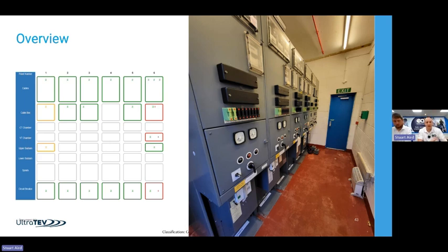So there are two totally independent tests, so we should always be doing a transient earth voltage test and an ultrasonic test to make sure that we can cover both types of partial discharge, both internal and just surface and corona type discharges. So this layout here is out of the software, so we can see each of these symbols. They indicate a TEV measurement, and they're all green. A couple of ambers at the end, probably a battery charger at the end of the substation.